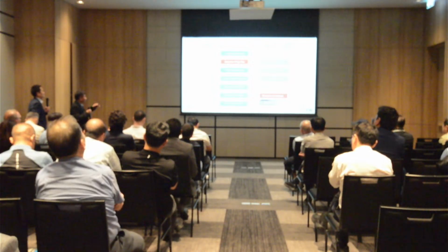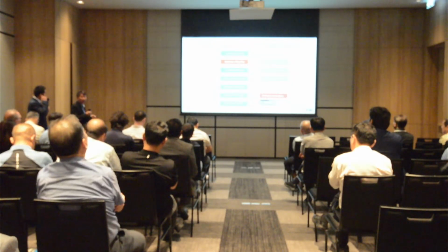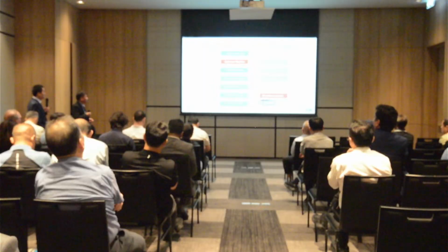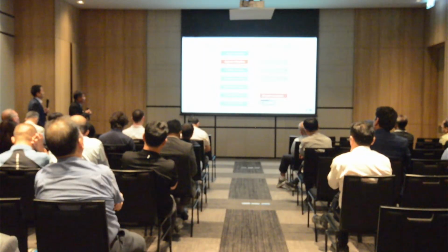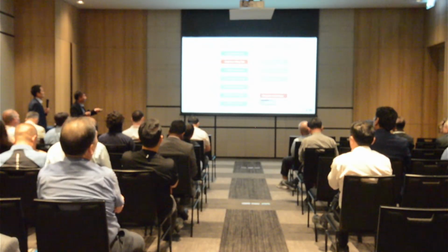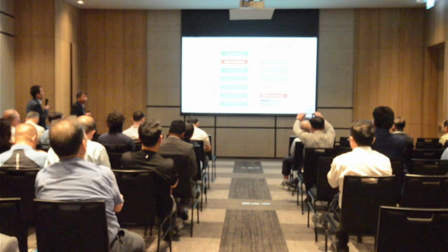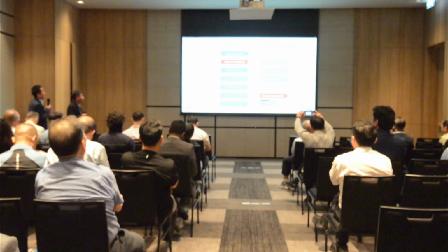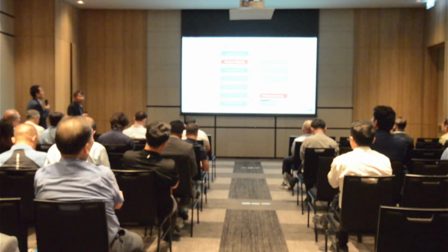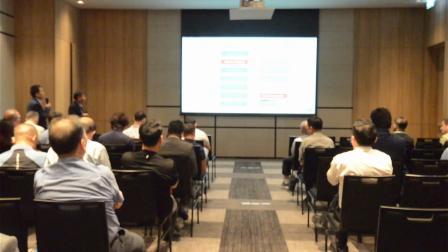And then find the right gate location and layout, easier for cutting and trimming. And the last is to design the overflow and vents. And then based on the PQ analysis, find the right machine size and the plunger. And when we finish this, we will do the simulation and analysis.